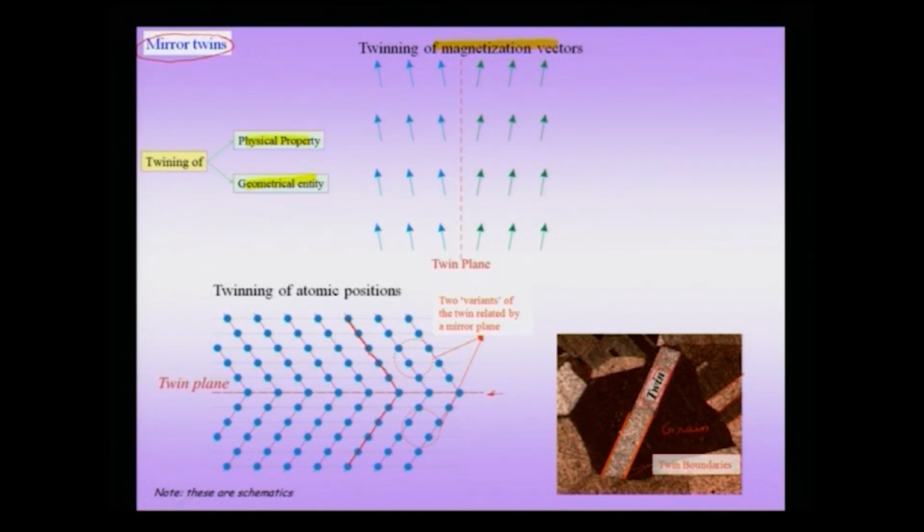The second twin boundary restores the orientation of the plane, and if I were to look at my atomic planes, I am just drawing some schematics here, they will be in the same orientation across the twin boundary. This implies that the twin interface, which is otherwise called the twin boundary, is one of the atomically sharp interfaces as compared to a grain boundary or other kinds of interfaces, which are typically somewhat diffuse.